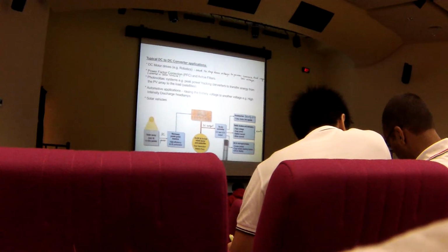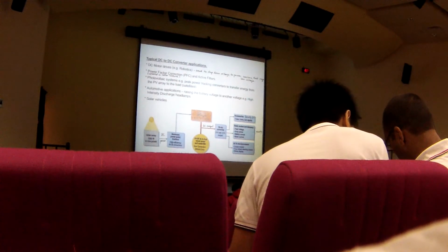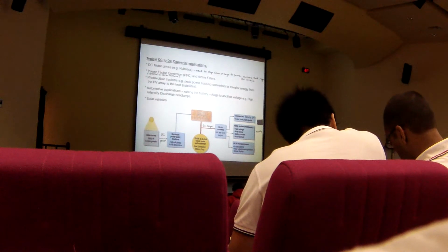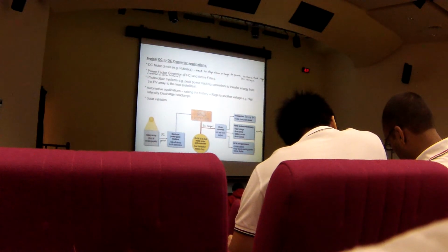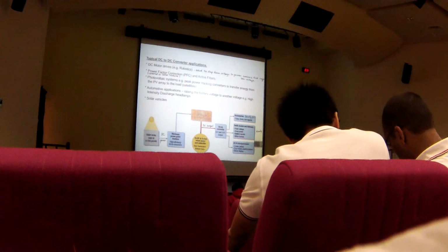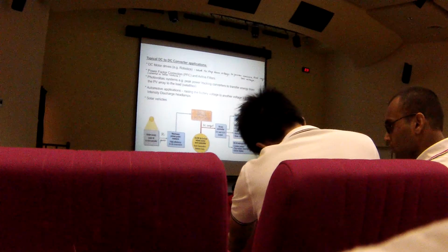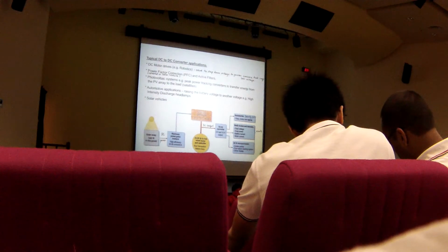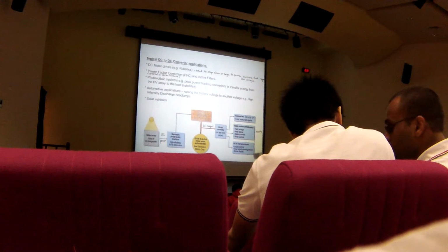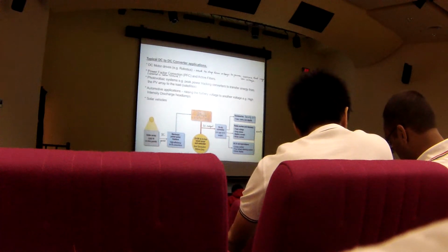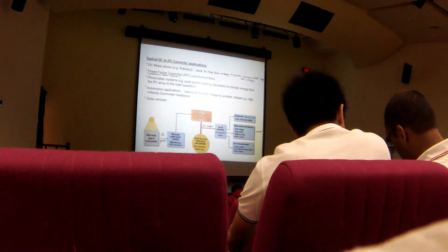And this DC output will be powered to a DC to DC converter, which will give you either 5 volts or 12 volts output, depending on what components you wish to power. So if you want to power accessories like fans or horns or signal left, signal right, this is usually 5 volts. Okay? Whereas for radio modem and microprocessor, the microprocessor which controls your cruise control, your 4-wheel steering system, and your driver display, these are usually 12 volts. Okay, so this is the way you use a DC to DC converter.